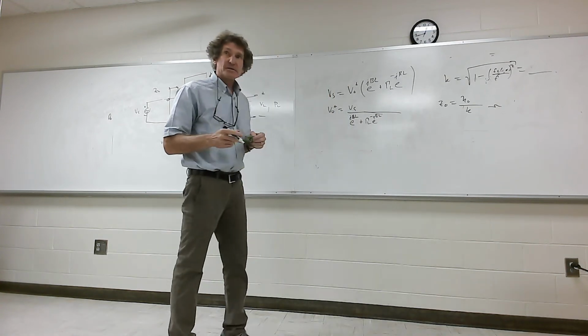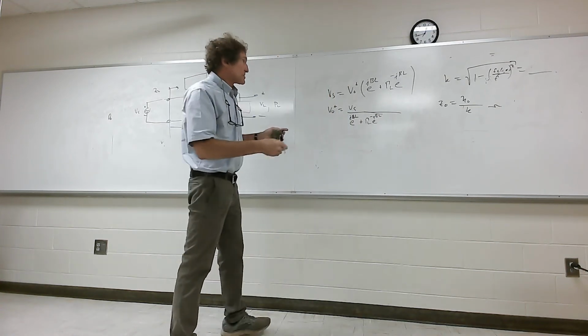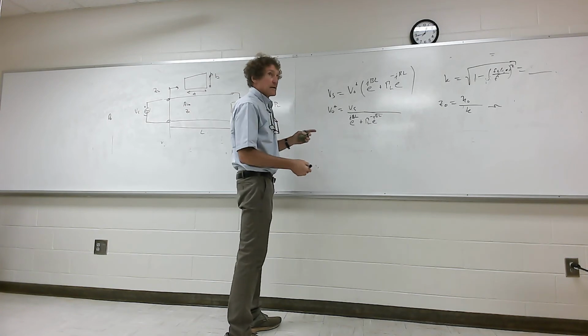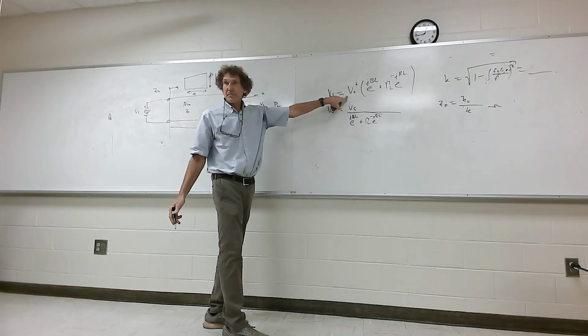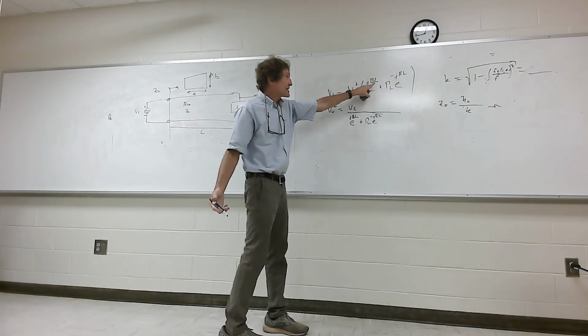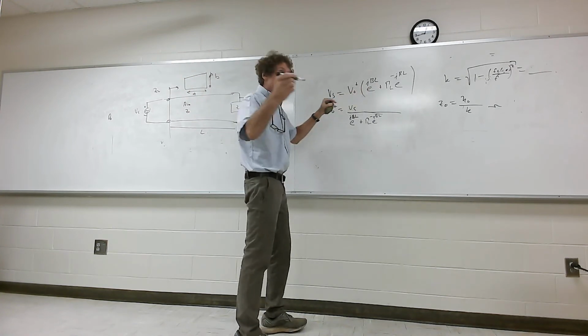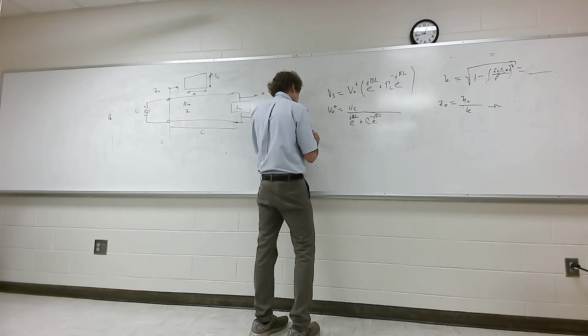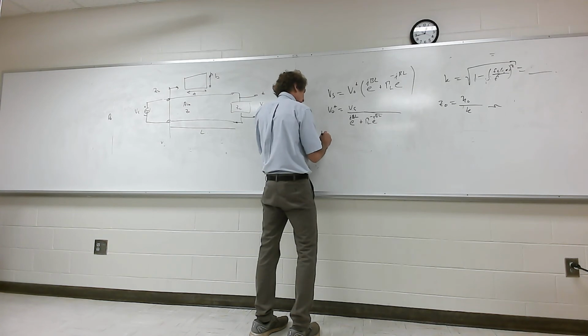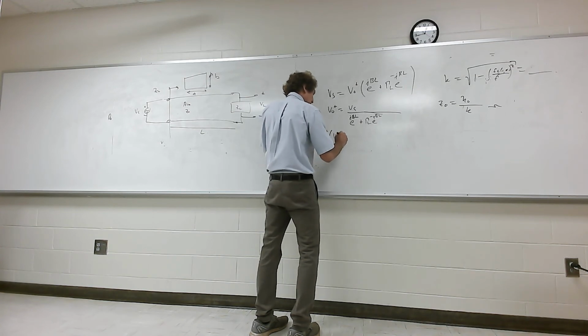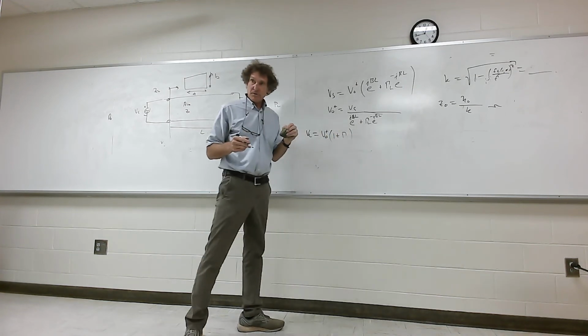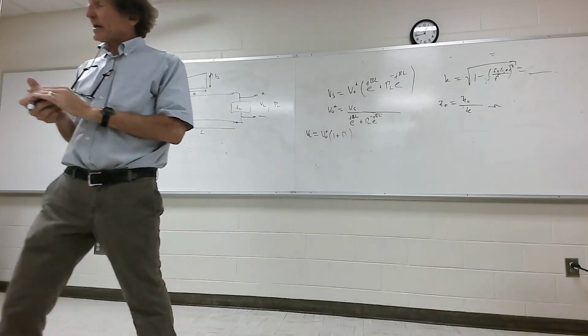Now, once you have this, how do I get the voltage at the load? Y'all remember this equation right here, class? The voltage at the load is when what? This L value goes to 0, correct, class? So then I can say, finally, voltage at the load for this one would be V0 plus times 1 plus the reflection coefficient at the load, correct? After I have that, I've got the voltage at the load.